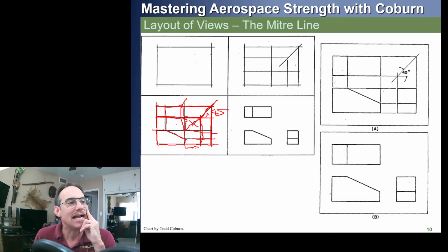And then, what we normally do, if you're learning drafting by hand, you're going to learn about line quality and how you can have a nice bold line for the edges of your part. And these leader lines are going to be really faint with a super hard and fine lead, so they hardly show when you go and photocopy this, so you don't have to do a lot of erasing.